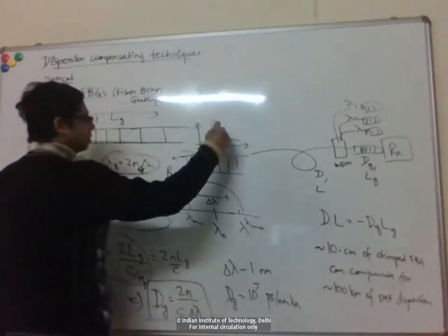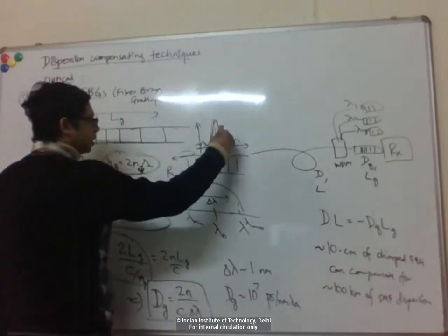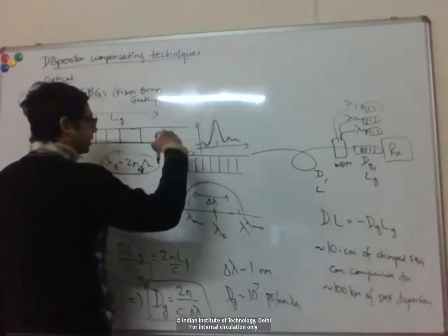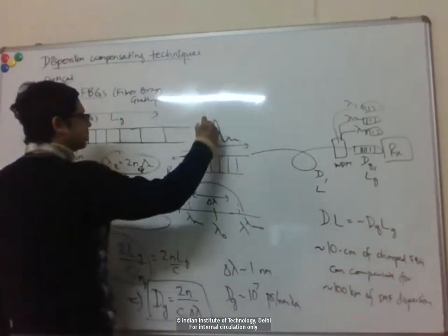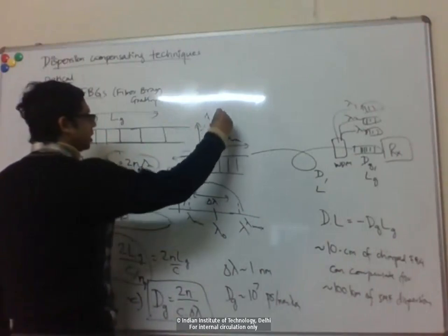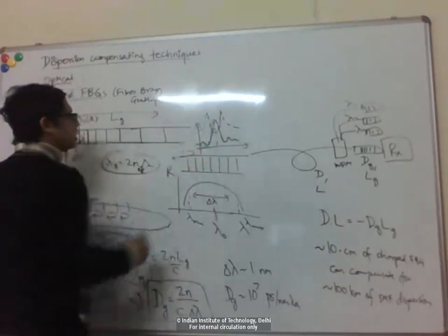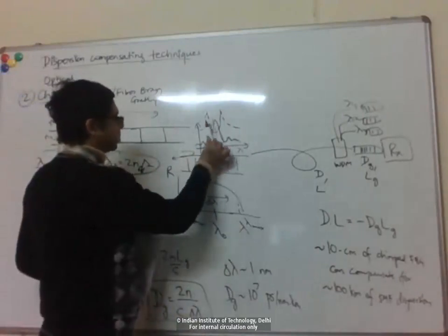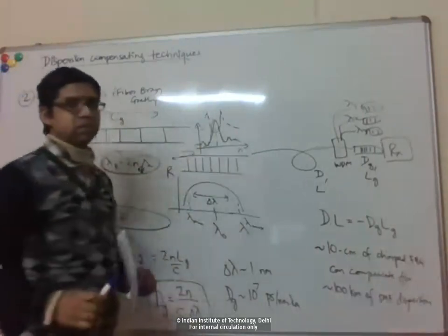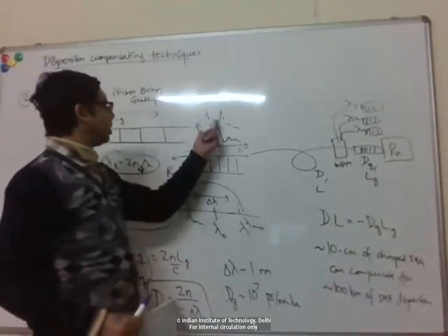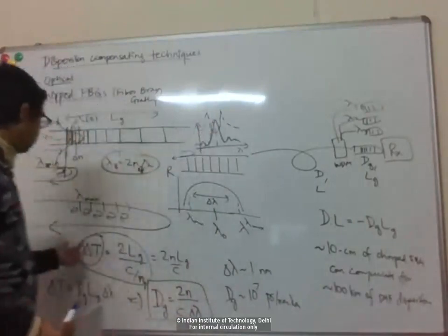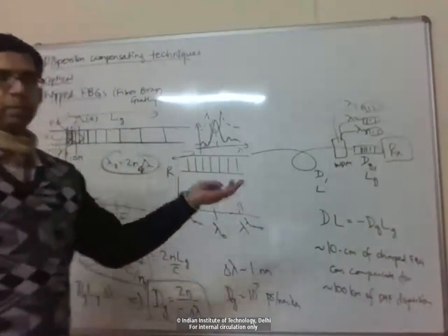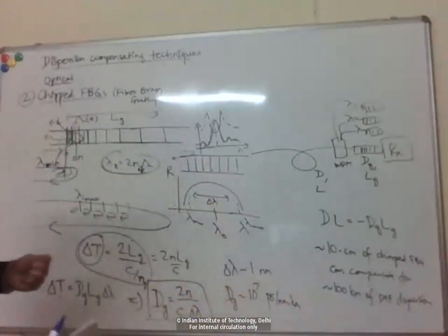This is the amplitude or intensity response, and there's also a phase response, which is roughly the derivative of this. The different wavelengths slightly away from resonance will acquire different phase shifts, and a phase shift can be looked at as a time delay.